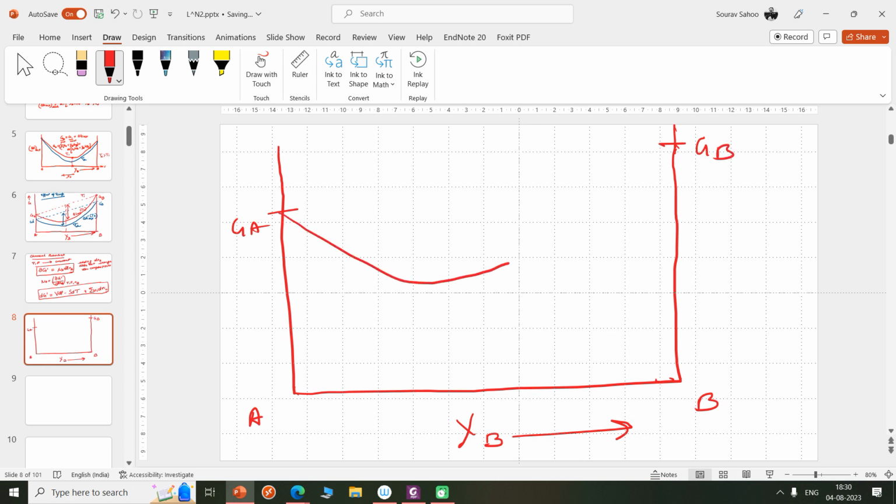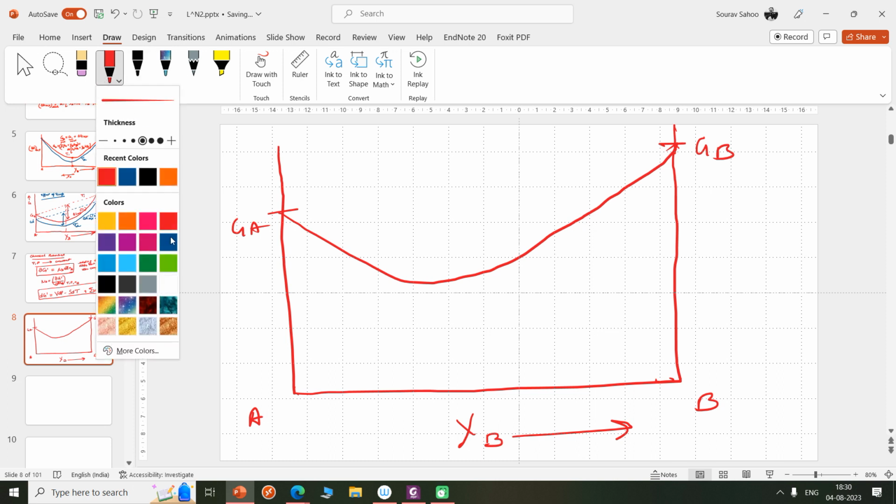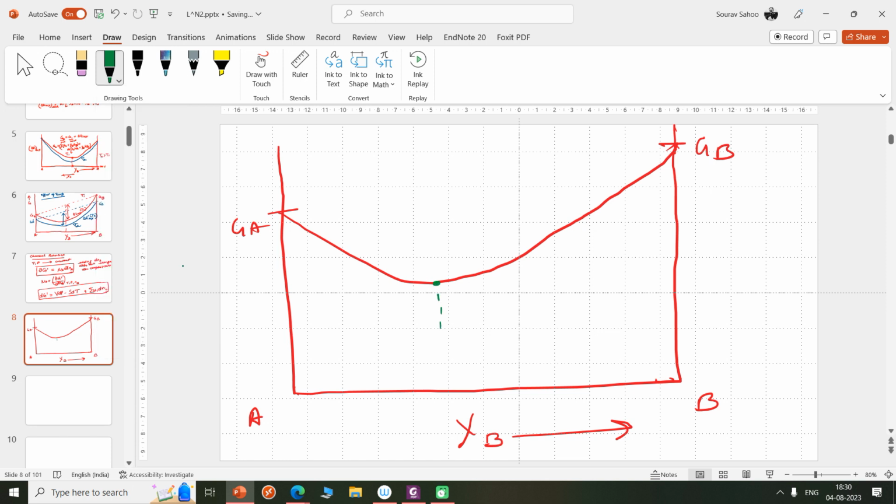And we have this free energy on mixing this way. So if we just take a tangent, this here is the point where my free energy is minimum. So this is actually the amount which will be stable in equilibrium. And if we just take a tangent at this point and let it cut the intercepts, this will give me the chemical potential of A. And we'll see in one of the numericals ahead how this can be derived.